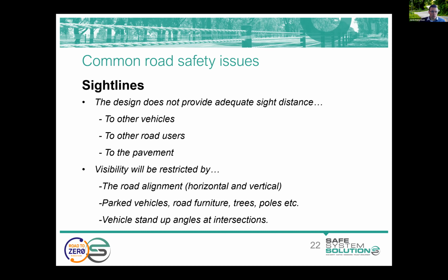Parked vehicles and roadside furniture often restrict sight lines, and parked vehicles is a bit of a contentious one. There's a school of thought that a parked vehicle is a sort of temporary obstruction. You ought not consider that in your sight distance checks, but I've undertaken many an audit where the presence of parked vehicles has been a significant safety issue, and the recommendation out of those audits has been to perhaps ban parking in an area or construct an outstand and bring forward a hold line on a side road to avoid that obstruction.